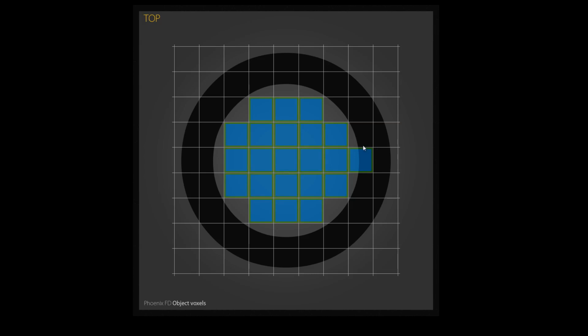And what the center mode will do is check if the center of the voxel is intersecting geometry. If it is intersecting geometry, it will act as the circumscribed. So this voxel here, you can imagine that its center is somewhere around here, so this one won't be filled with liquid. And if you take a look at this one up here, its center is somewhere around here, so this one will be filled with liquid.